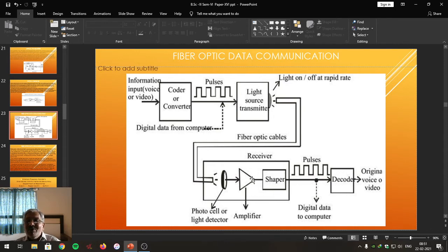This amplitude varying signal is compared with threshold signal by using sample and hold circuit. If suppose incoming signal is equal or more than the threshold level, that will be treated as a 1. If the incoming signal is less than that of threshold voltage level, that signal will be treated as a 0.